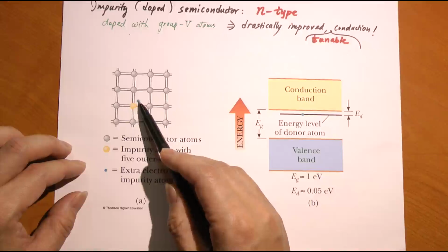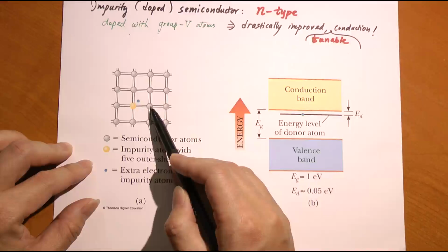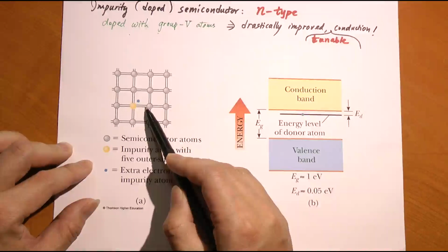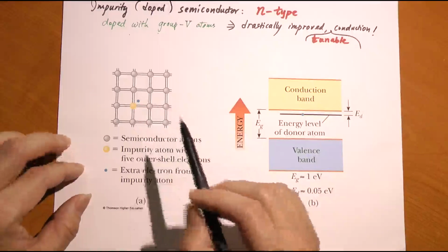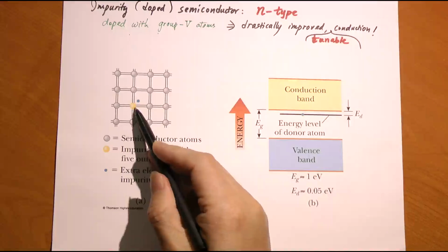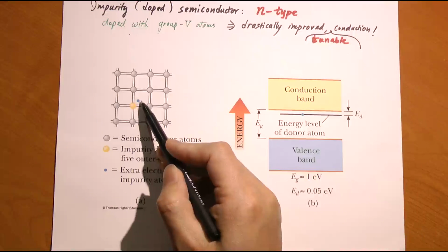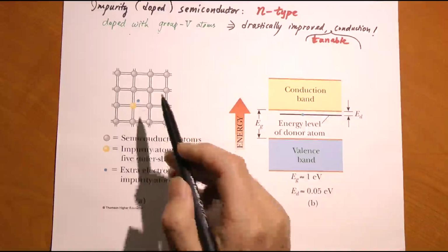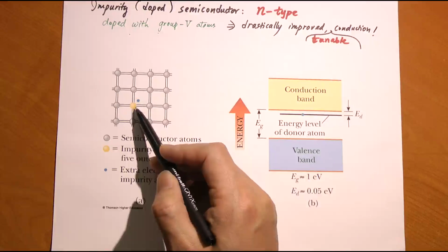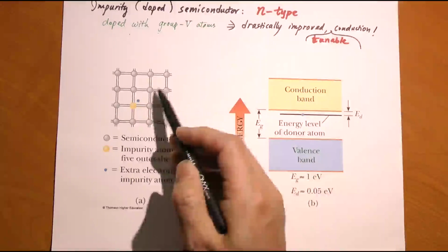So it's got an extra valence electron, which is kind of useless because the surrounding atoms are all group 4 atoms. So we have 4 valence electrons, one contributing to each bond. This fifth one is like an orphan. You don't quite need it. This group 5 atom does not quite care about this one extra electron because it's not that useful. Now, it doesn't mean that it doesn't want it, because there's always still a Coulomb attraction between positive and negative. So it's not like it's entirely free, where it will just get out of here by itself.